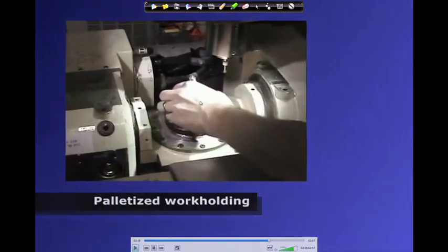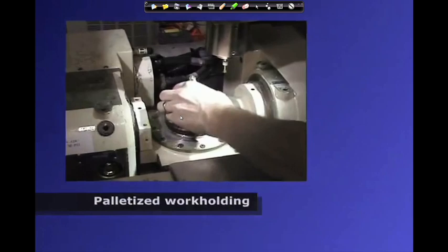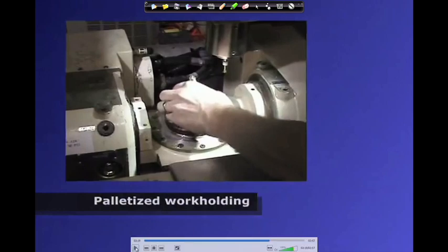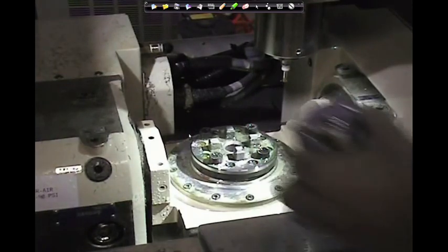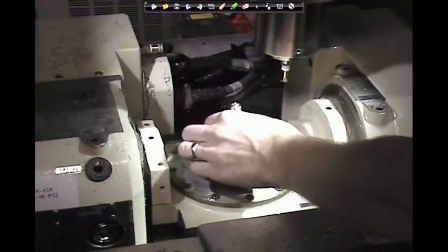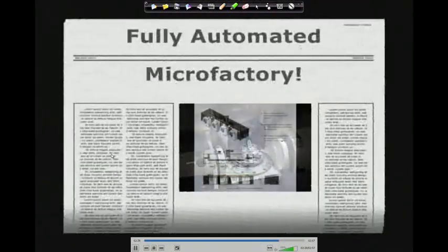And this movement or the fixturing is also pneumatic, so that you do not need to press anything very hard on the top. It is a pneumatically operated or vacuum fixture. So, clamping and declamping will be very easy and convenient without giving any type of extra force. So, this is how this thing works.